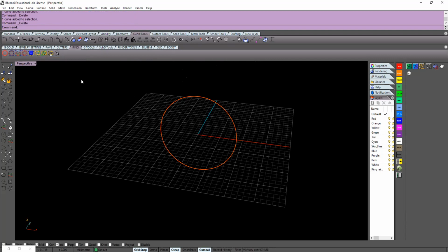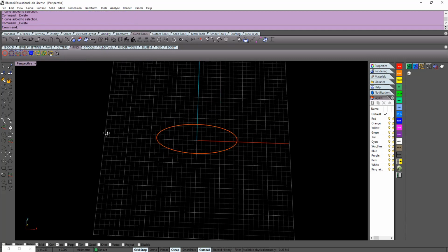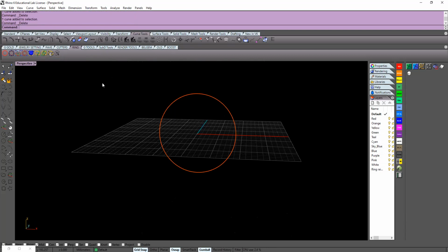Step 2, add your main stone. So when we're making a solitaire ring, often you'll want to use a die struck head. What that means is you would create your CAD file and print your file that doesn't have a head in it, and you'll buy a die struck head. The reason is die struck heads are stronger than cast heads. Also, if you create a mounting that you can put a separate head in, you can put different size stones in there, so it's more versatile.